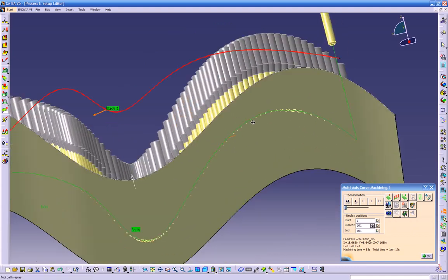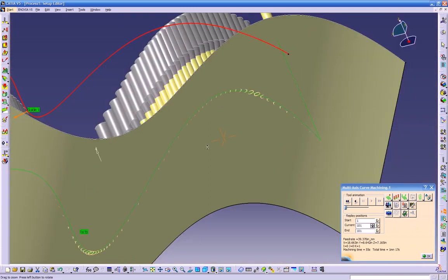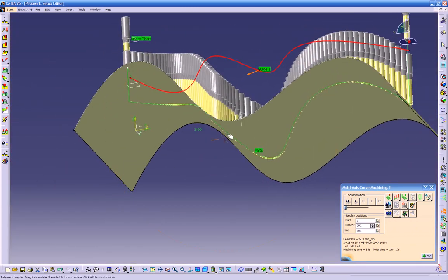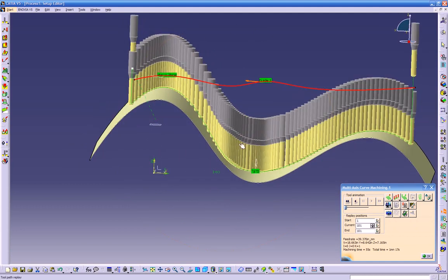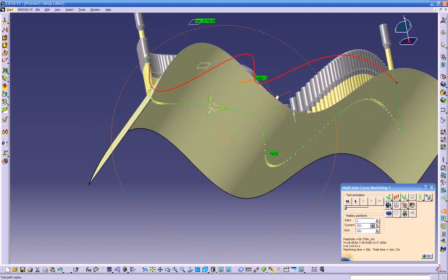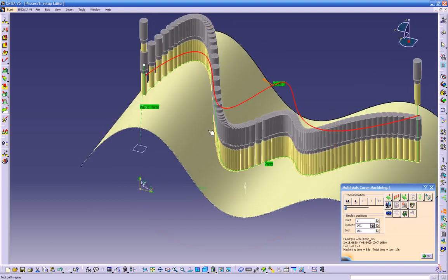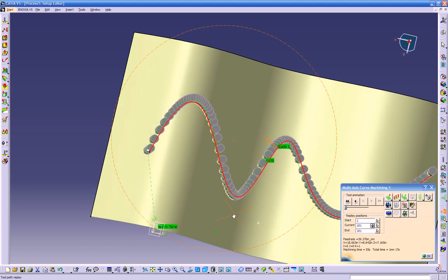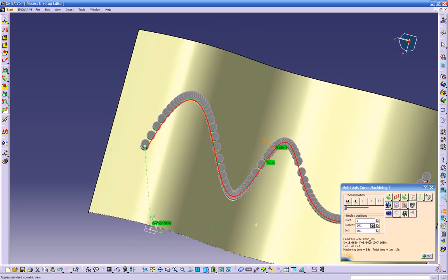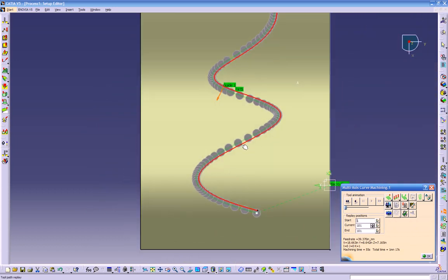So this is how this works right now. Look at the difference. See the tool right now? It does not gouge into the part because it knows that this is a surface. So what we did is use this curve and project it straight into the surface. So if you want to have a nice profile, this is where you're going to come and change it. But also, see how much control we're going to have over this. Right now, if we do a top view, see the tool right now, it's on the outside of the line, but we can change it, we can offset this.